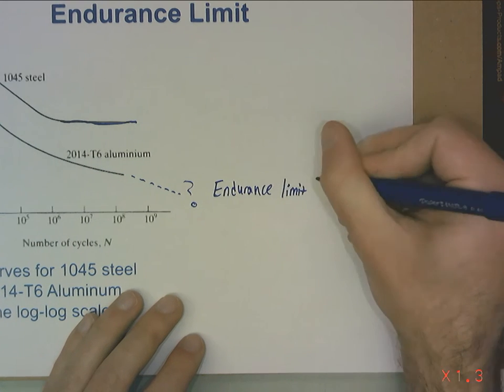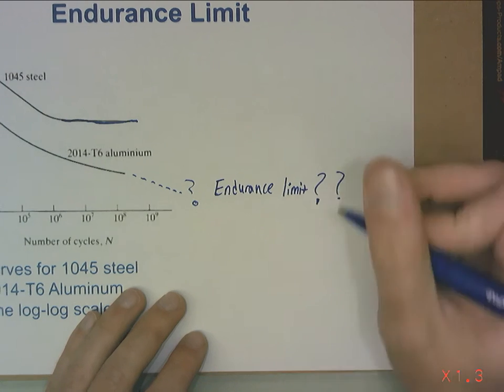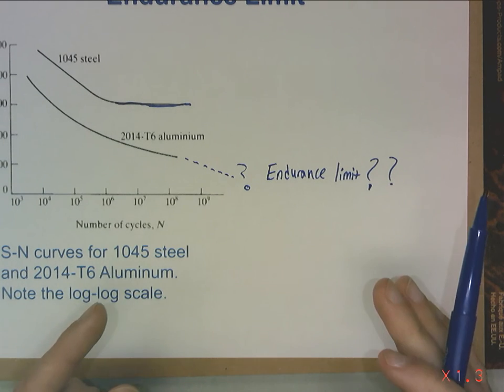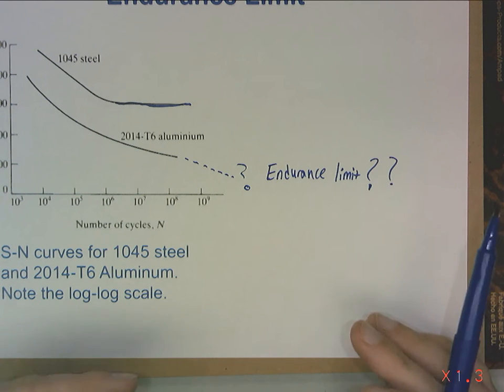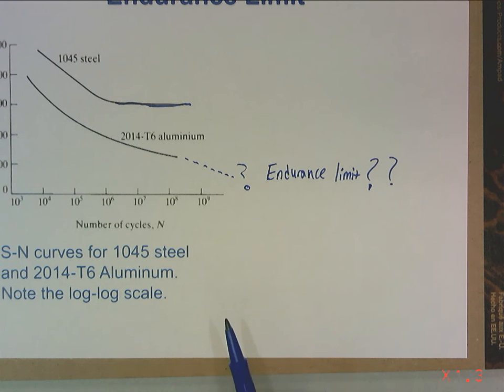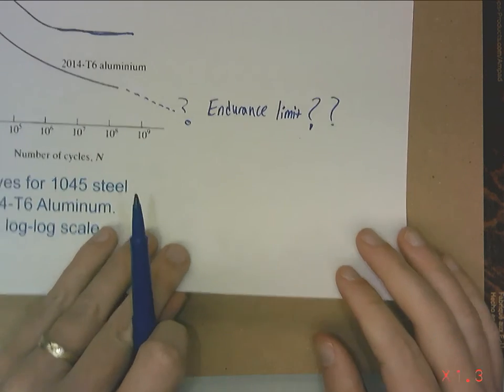Realistically, aluminum has an endurance limit. I think if you just took a bar of aluminum, attached it to a motor, and just started rotating it under its own weight, I don't think we would really expect that to fatigue fail, right? It's just aluminum's endurance limit is low enough that we often consider it to not have an endurance limit. So, if you've ever been on a plane,